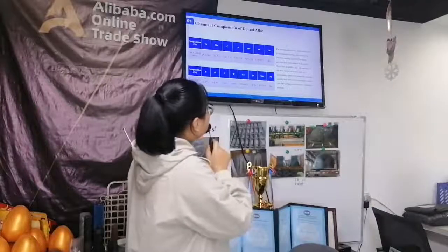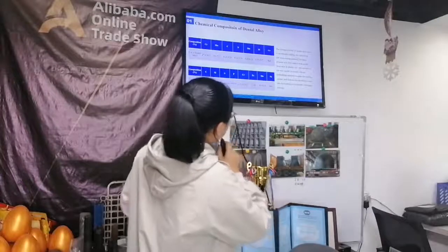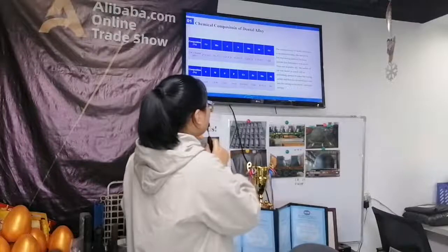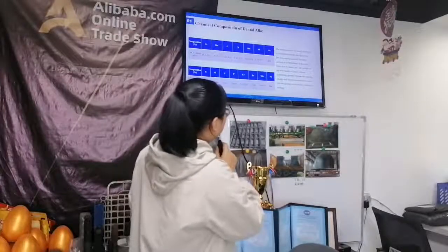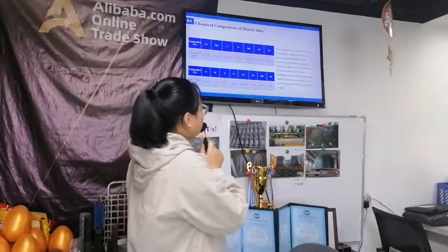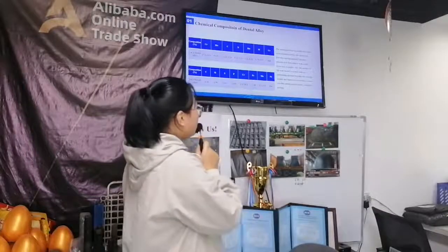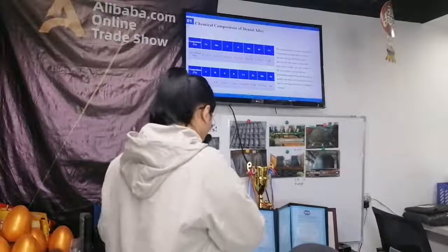The basic process is to first make a wax model from wax or plastic. The surface of the wax model is coated with an embedding material to make the casting model, and then the molten alloy is cast into the casting cavity inside, forming a casting.